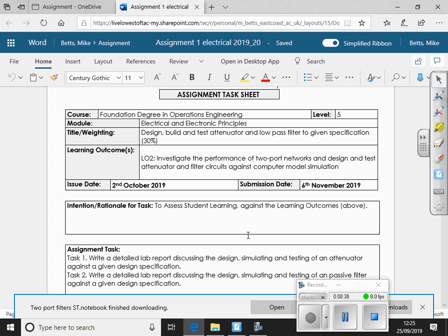One of the things I always say, and I always get people go against it, is a photograph of the equipment is not a replacement for a proper circuit diagram. Because the idea of a lab report is that the person reading it might want to repeat your work with slightly different equipment. So a proper circuit diagram showing where any meters were connected, in a normal standard format, is really important.